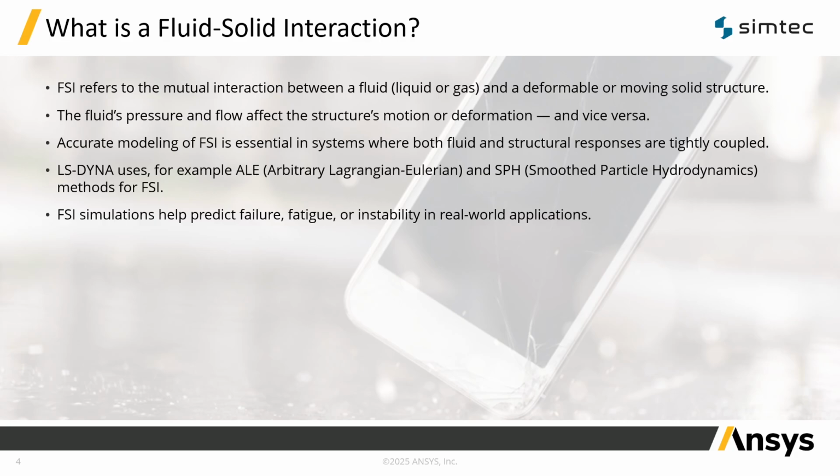In LS-Dyna, FSI is handled through multiple formulations, for example, ALE or Arbitrary Lagrangian-Eulerian for mesh-based fluids, and SPH or smoothed particle hydrodynamics for mesh-free simulations. FSI simulations help predict failure, fatigue, or instability in real-world applications.